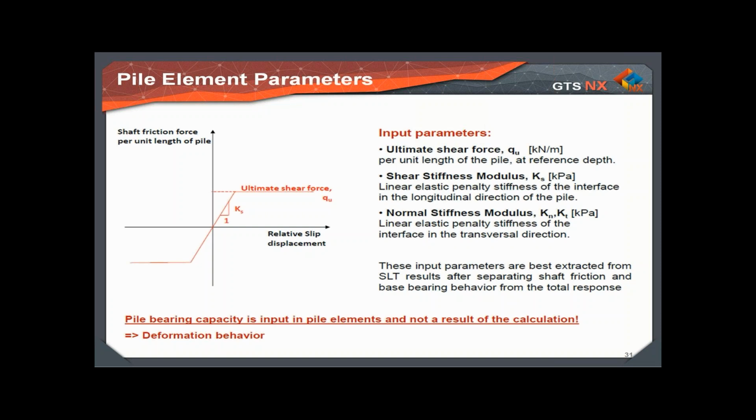So this ultimate shear force, you need to get it from, if you have a pile loading test, the curve. You can separate the shaft friction from the base and the base from the total load-deformation behavior and assess your ultimate shear force for skin friction.